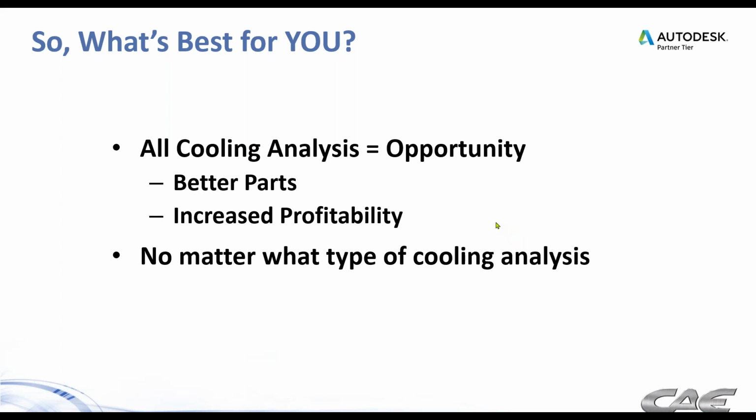Warpage analysis, we'll talk about it in the next seminar or webinar, but one of the first things I see molders look to when it comes to warpage is the cooling, and rightly so in many cases, but you don't know until you get into it, right? And that's what mold flow analysis helps you flesh out. How much of your warpage is due to the cooling? But there are other things too, cycle time being the biggest one of them.